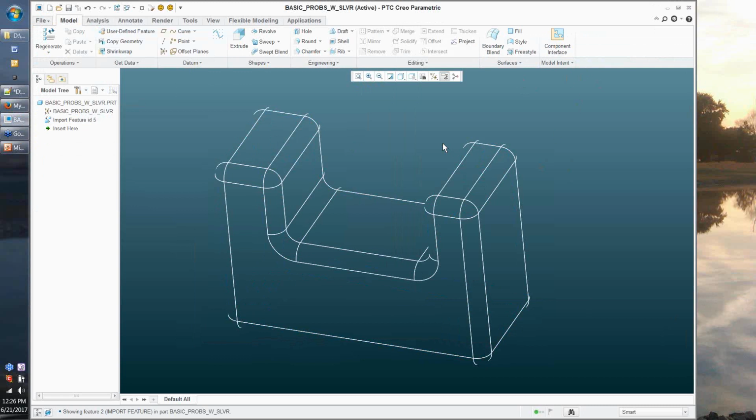The originating system declared it to be, in this case, 0.066. If we were to use 0.1, geometry that we would create moving forward would be no better than that 0.1 value that we use. But it would be not likely to negatively impact the ability of the system to import the file without errors and without increasing the number of open edges that are viewed on the imported file.